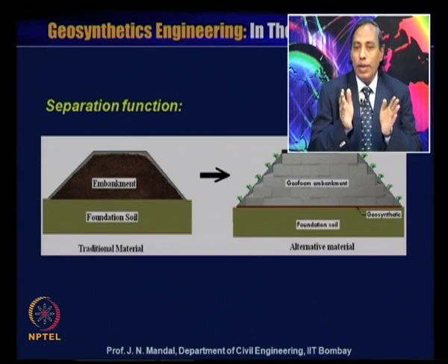You do not need any kind of excavation, and the design is very simple. The design is based on the density of the geofoam, what the thickness of the geofoam will be, and their different mechanical, chemical and also environmental properties. Here the geofoam acts as a separation function.